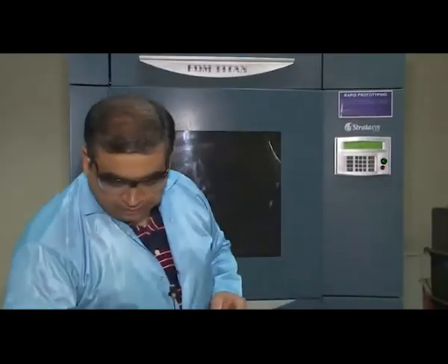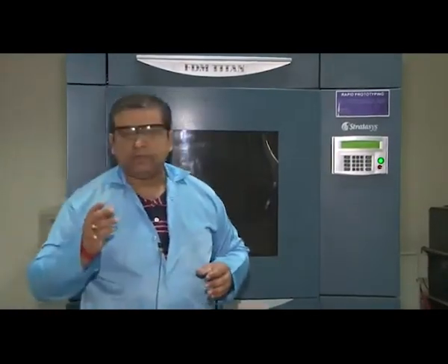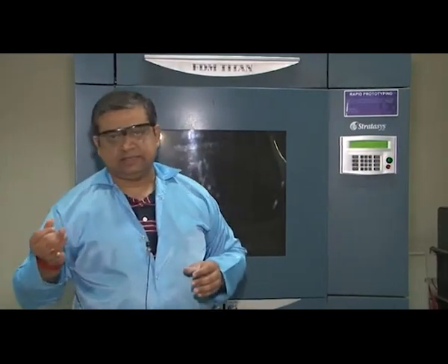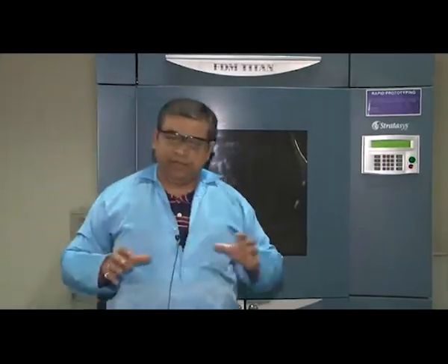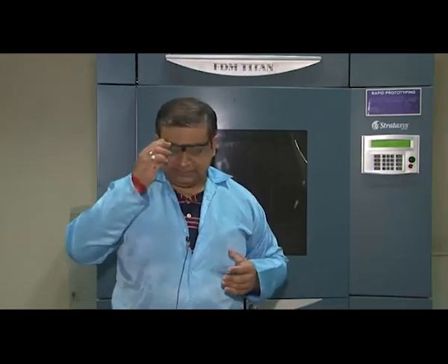Okay. So in a nutshell, what I am trying to say here is that there are a lot of advantages associated with rapid prototyping. One of them is of course the high level of customization, another is the ability to handle complex designs or parts. Third is a lot of material saving, because it is a layered model and there is no secondary material which is wasted in the process. And then this can formulate an intermediate process for final primary manufacturing processes like forming or casting, where probably you have to do the mold development or the die making. So some kind of a prototype is needed, okay, in order to envision and design such a system.